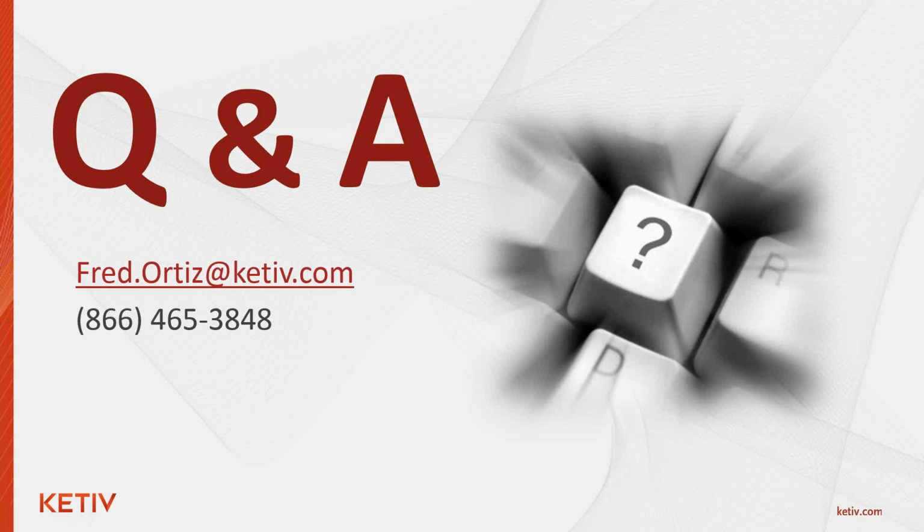And I got one more question. What was the difference between a host-based family and a standalone family? I think I talked about that as well, but just to reiterate, a host-based family is pretty much dependent on a host, such as a wall, ceiling, floor, a roof, or a face. Kind of like the light fixture we just created, that was a ceiling-hosted family. And a standalone family doesn't necessarily need a host, and those things are pretty much like a chair or a table or some type of mechanical equipment you place inside of a building. It doesn't necessarily need a host to be inserted. So that's pretty much the difference right there.